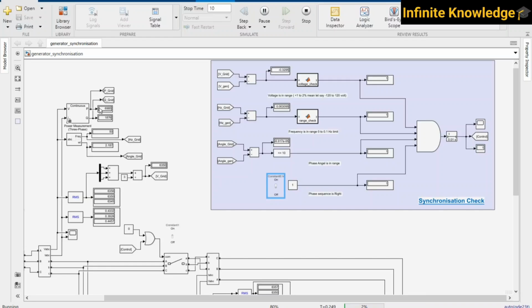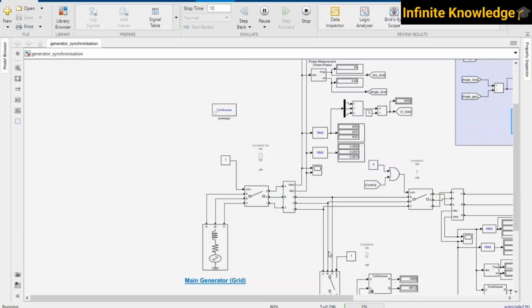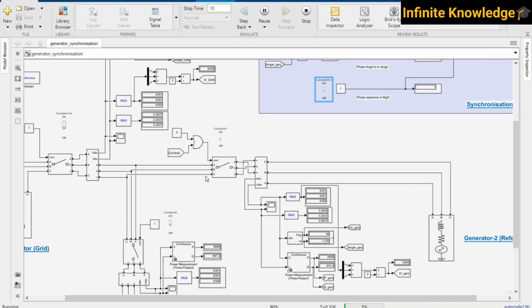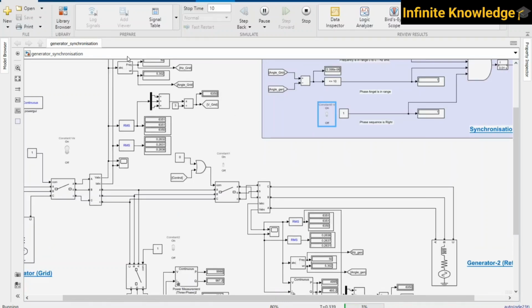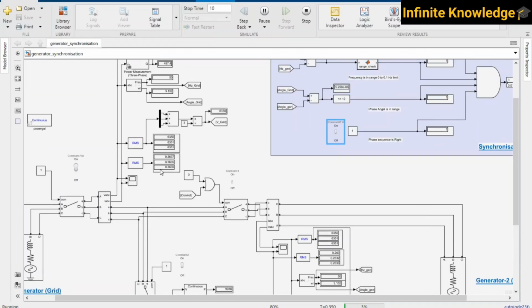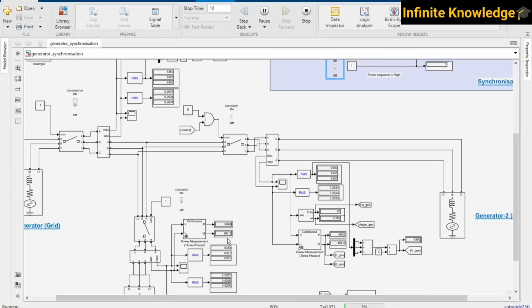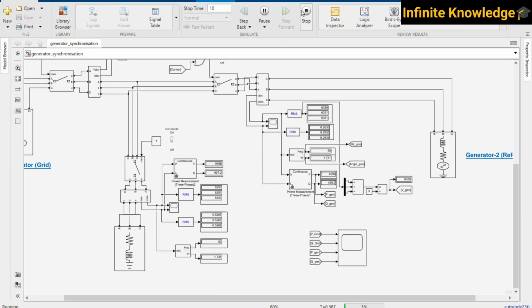Okay, the breaker is started. You can see the power is reduced. Why is it reduced? Current is also reduced because initially all the current was taken, what was being fed by this generator, but right now this generator also comes into the picture. This breaker is on, so the load is divided between both generators at 0.26, 0.26, and we are getting finally this much amperage.